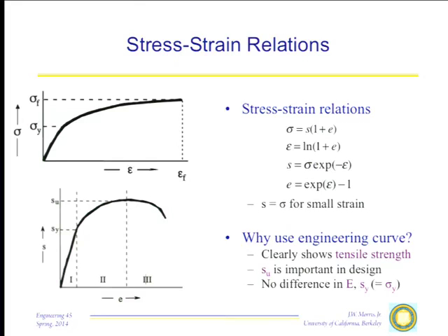Otherwise it would deform, and if your car were designed to go out of the elastic region when you were driving down the road, it would look like Dali's clock in no time at all, and would not be a functional vehicle. So virtually every operating piece of machinery, every structure is designed in the elastic region. In the elastic region for these metals, the total strain is very small, and you can easily show that the engineering stress and engineering strain are identical to the true stress and true strain. It just doesn't matter which one you use.